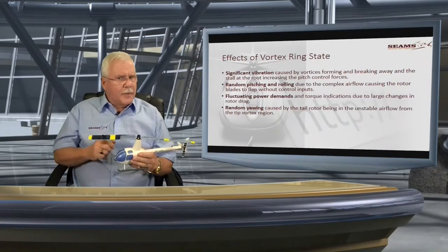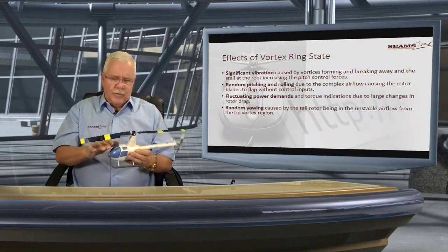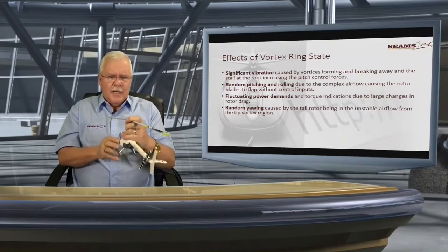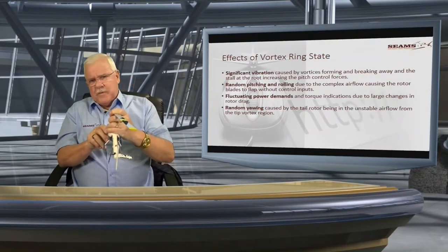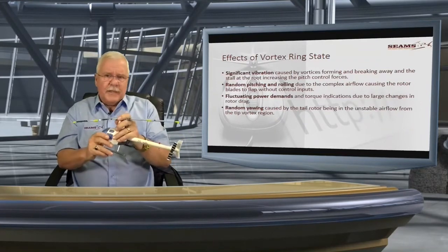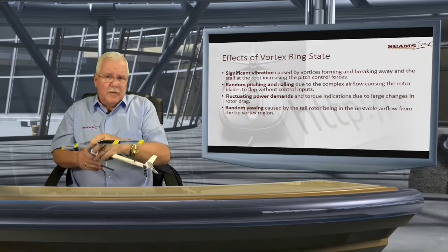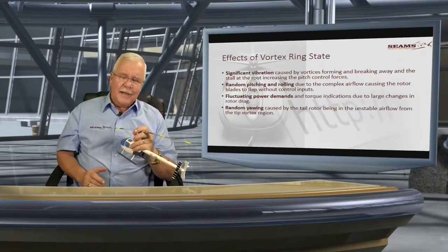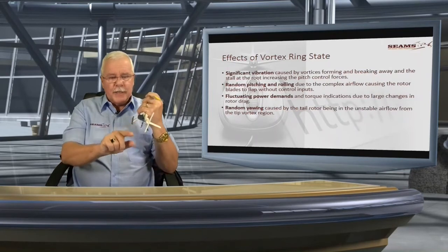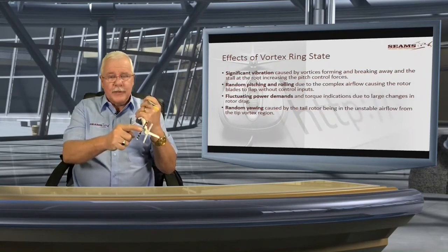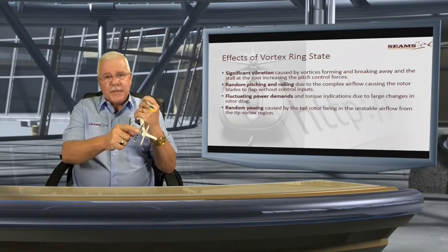But there are some other serious maneuvers. The guys say if you sit there in the vortex ring, you torque it and you bank it and you bunt it. And guys, this thingy at the back here, called a tail rotor, maybe it takes up 8% of the power.